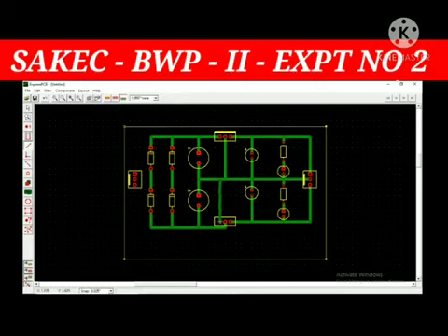So I am connecting this diagram. Now this is my transformer, this is my secondary upper line. I will connect to these diodes. This is my secondary second line. I have to connect this to this. Now this middle terminal is ground, and I have to connect that middle terminal here. I cannot connect like this, because if I connect like this, at this point it is shorted. So I have to use another option. I can select like this. So you have to show your art to connect these wires.